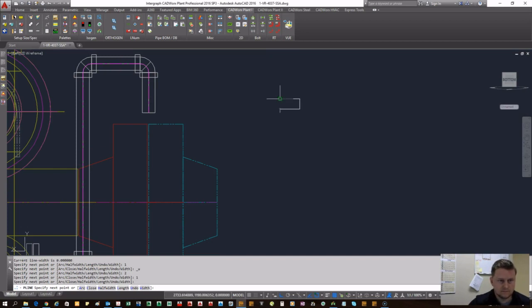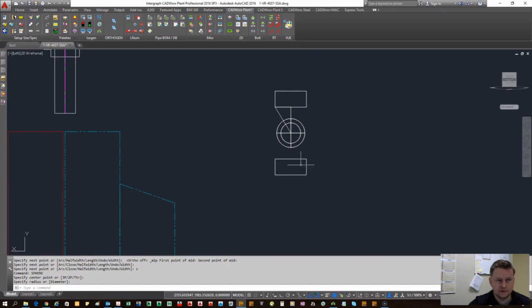So let's say that's our hub part for the valve that we want to create, and let's say between these 2 points. The entire time when you're creating this, you want to start off with 2D stuff so you can size it up just right given your cut sheet. So here I've created some really basic 2D objects that I'm going to revolve to make them into 3D. Here we have a hub and our center body. So we're going to revolve those.